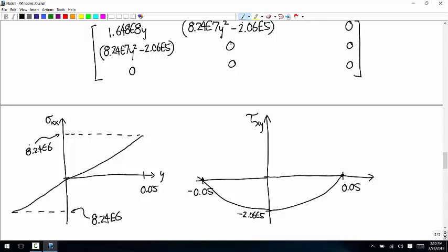So for our purposes, let's just figure out what the values are here and here, and we'll pretend that this isn't here at all, okay? Really, it would be a point a little away from there, but we're going to say that this is a pretty good guess for where the stresses are going to be high. Anybody have any questions about that thought process? All I'm doing is saying the biggest this one gets is something times 10 to the 5. The biggest these get is something times 10 to the 6. I'm going to be more concerned about this one. So we're more concerned with the magnitude.